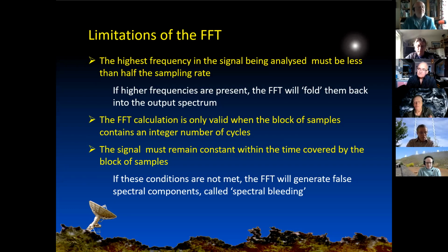And secondly, the signal must remain constant within the time covered by that block of samples. And that's a finite time, and it can be a long time. So these really make it impractical, in its purest sense, for realistic signals in practical signals. And what happens is that the FFT generates false components, something called spectral bleeding.